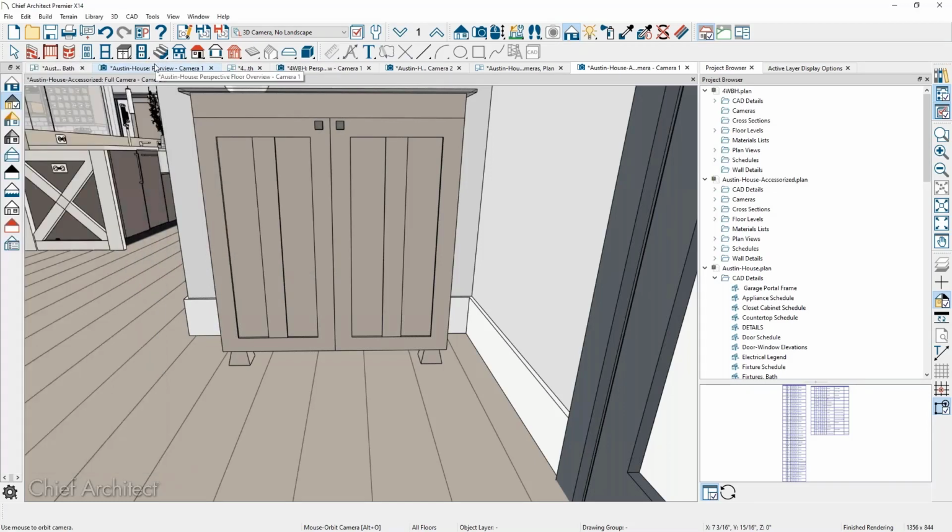Anybody that does anything somewhat serious for kitchen and bath design, I always recommend you turn that off. We turned that off, I think, in our interiors template. If you're serious about doing kitchen design, those aren't easily dimensioned to. They don't show up in your materials list. I usually recommend people turn those off if you're doing detail in kitchen or bath design. So that's a good place to turn it off in your default settings. And if you save that in your template plan, then your future projects would abide by that setting.